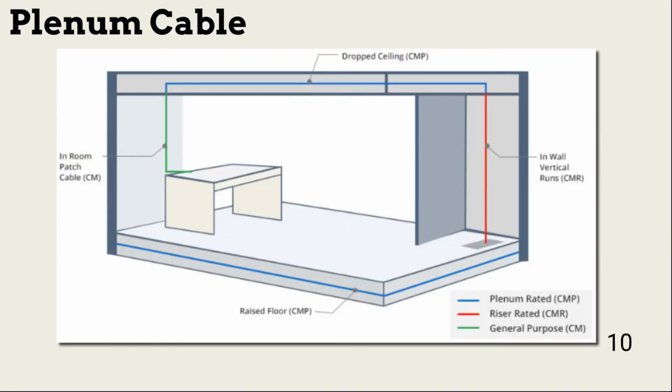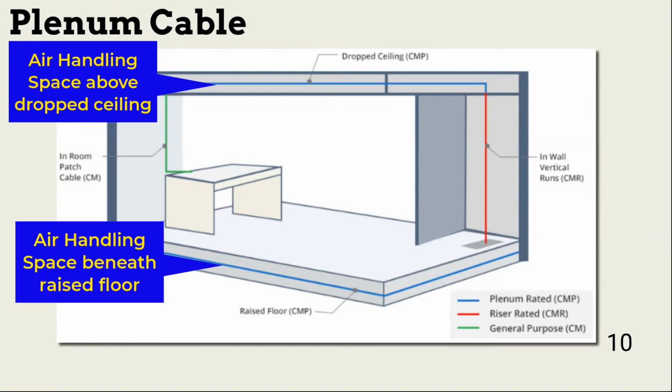An example of regulatory requirements for cabling is plenum cabling. Regular PVC used in standard cabling releases toxic fumes when it burns. Using PVC cabling in air handling spaces is a violation of fire or other codes. Examples of air handling spaces include spaces above suspended ceilings, assuming that air is not moved through that area via dedicated air ducts, and the area beneath the floating floor.